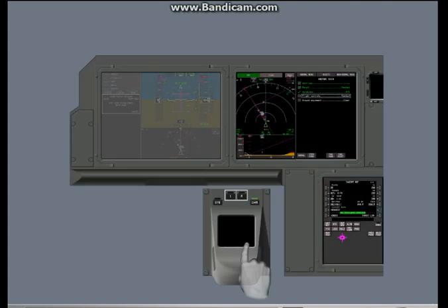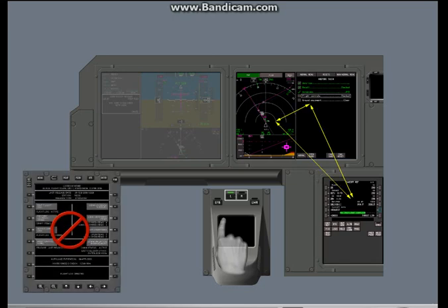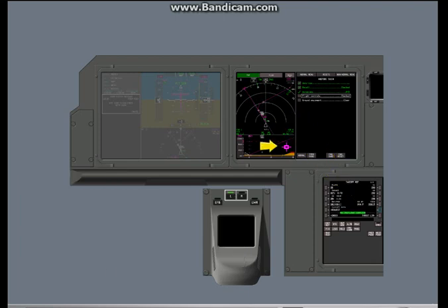You can also move the cursor to different displays with the CCD touchpad. If you slide your finger quickly to the edge of the touchpad, the cursor will jump to a different window. You can use the touchpad to move the cursor to and from the left, right, and lower windows. The touchpad cannot be used to put the cursor onto the EFB. When you lift your finger from the touchpad, the cursor movement stops. It does not automatically move to an active area.